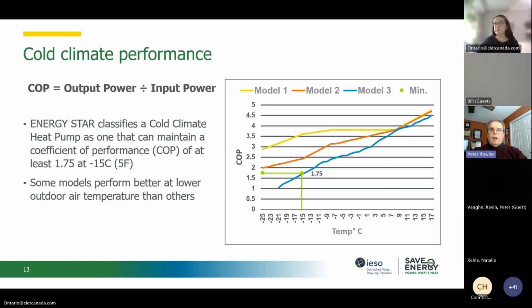This graph here shows the difference in performance, and that it can differ by different models. Even at sub-zero temperatures, the air contains heat. With moderate temperatures, the performance of an air source heat pump is very different. As the temperature drops and the delta T set point increases, the performance does degrade. But studies from Scandinavia have shown that even at minus 25 to minus 30, the COP of an air source heat pump can exceed 1, which would be equivalent to 100%. And that's more efficient than the most efficient furnace, boiler, or electric resistance heaters.